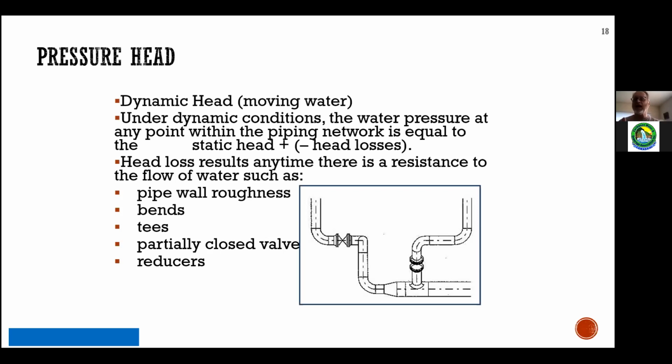So if you had all day, imagine a 45-gallon drum or a barrel, and you want to fill it, and you have totally unrestricted flow with 90 meters of elevation. You're filling the barrel in 5 seconds, 10 seconds. Switch the pipe to a smaller diameter pipe or badly rusted galvanized pipe, or one where the valve is 3/4 closed. It might take all day to fill it, right?